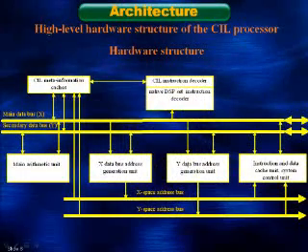From the hardware point of view, there is a DSP processor which has all classical attributes, like dual address and data buses, dual address generation unit, and a high-performance multiply-accumulate unit. The processor has two instruction decoders. It allows decoding of native DSP and native CIL code. Execution of CIL code is supported by internal control buses for access to meta-information and additional direct-mapped caches intended for caching of the most used object and class information.